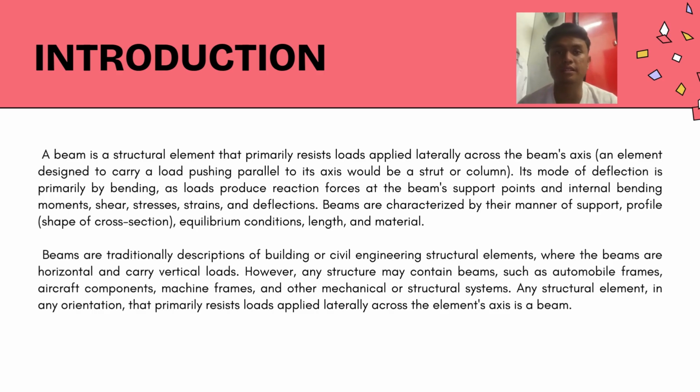This is for introduction. A beam is a structural element that primarily resists loads applied laterally across the beam axis. An element designed to carry a load pushing parallel to its axis would be a strut or column. Its mode of deflection is primarily by bending, as loads produce reaction forces at the beam's support points and internal bending moments, shear, stresses, strains and deflections.